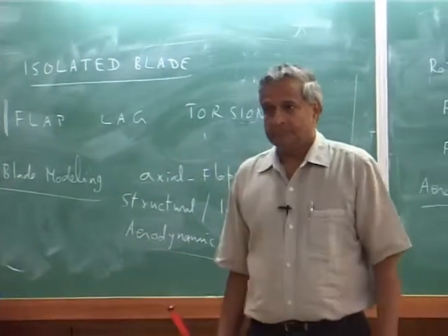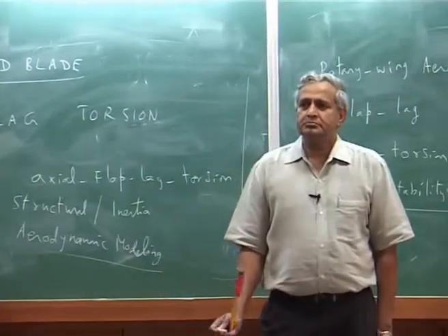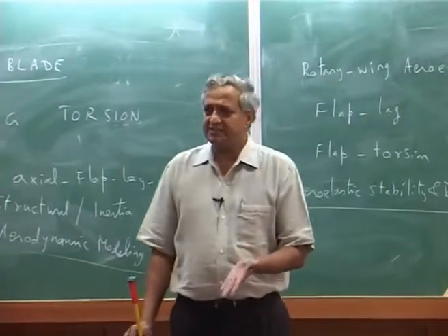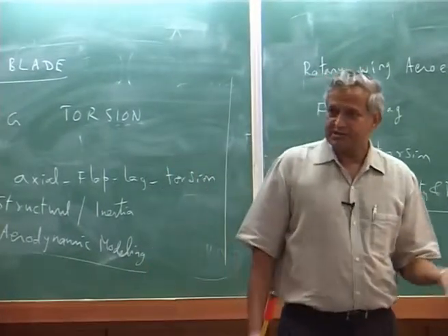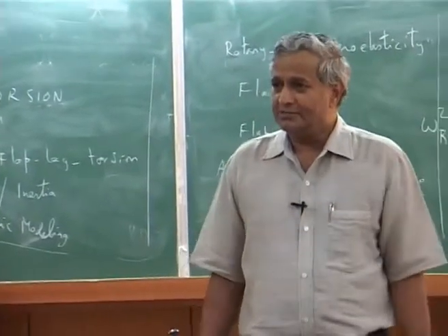But my question was, say, this K beta we are estimating, would it be of orders less than, say, EI, the blade stiffness? Definitely, dimension wise they are different. Dimension wise this is Newton meter per radian. That is what? EI is what? Newton meter square.